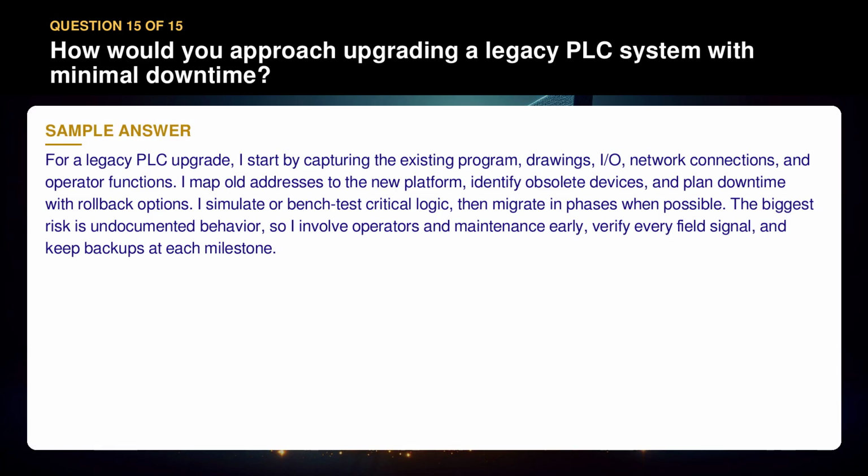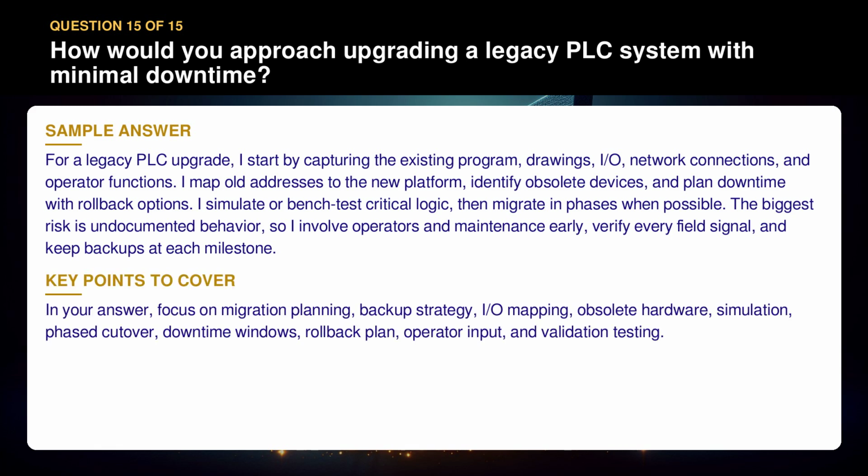The biggest risk is undocumented behavior, so I involve operators and maintenance early, verify every field signal, and keep backups at each milestone. In your answer, focus on migration planning, backup strategy, I/O mapping, obsolete hardware, simulation, phased cutover, downtime windows, rollback plan, operator input, and validation testing.